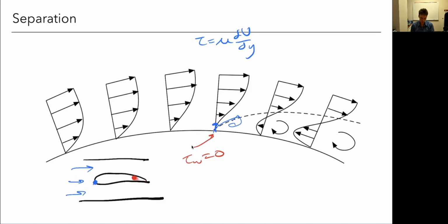So you'll notice that there'll be a complex fairing, right? Kind of a gradual transition so that the flow does not stop here. It will accelerate, kind of curve onto the wing. Same with like a winglet on a wing, right? We'll see kind of these, not just a straight edge, but some complex fairings.